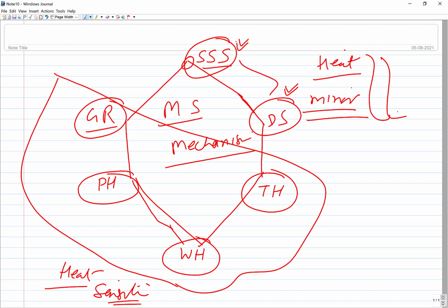Similarly, a minor loss of the work hardening effect imparted during the manufacturing of those metallic sheets may also be neutralized. But since the metal is strengthened by dispersion hardening or solid solution strengthening, the loss of work hardening or the loss of properties due to minor grain coarsening will be minor. Okay, so in these two cases the effect of heat is negligible.